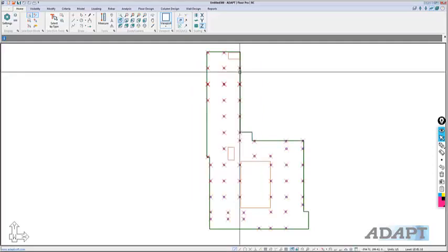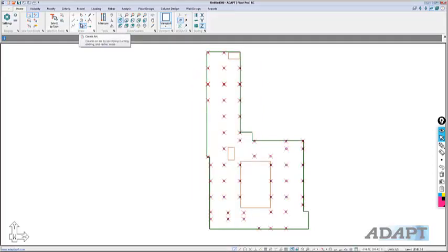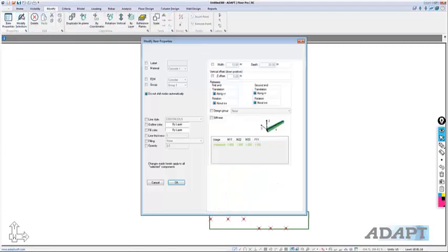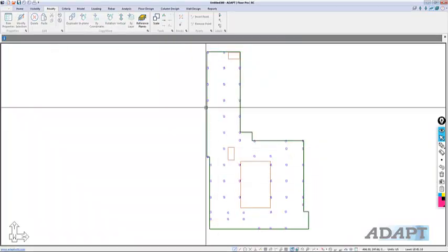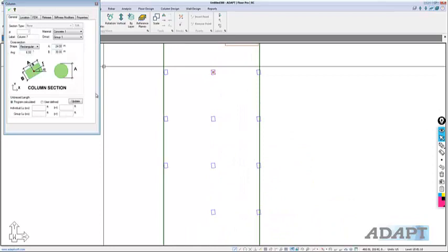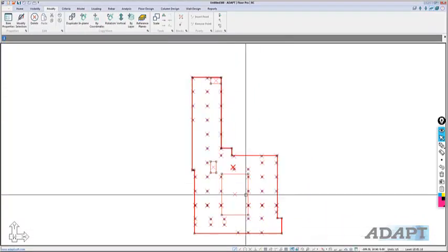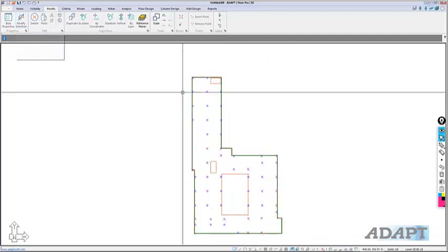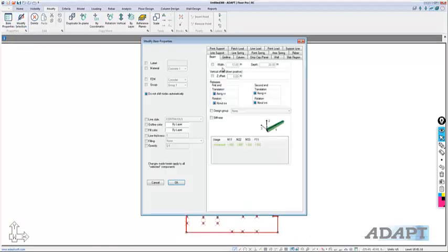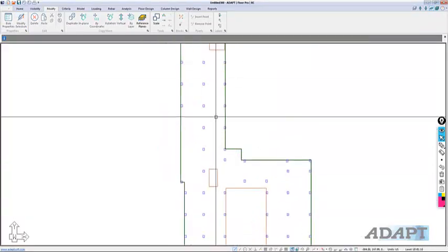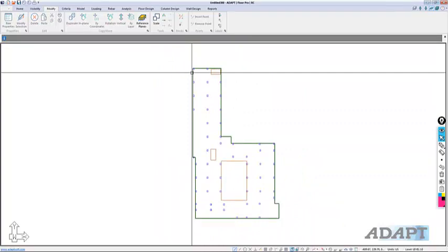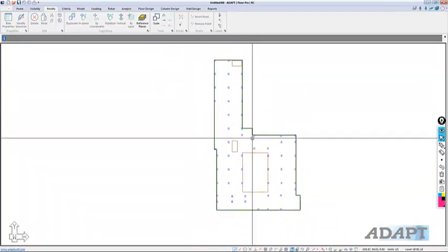We'll select our columns. And since we're modifying more than one component, I'm going to go to Modify, Selection. Okay, and under Column, the rotation angle we'll say is 6 degrees, or excuse me, 276. Let me just check a column. So that's 6. Actually needs to be 0. Let's try that again. I'll just window select this, modify selection, column. This should be 0. Okay, now they're aligned. So the rotation didn't realign the columns when we had rotated the slab.